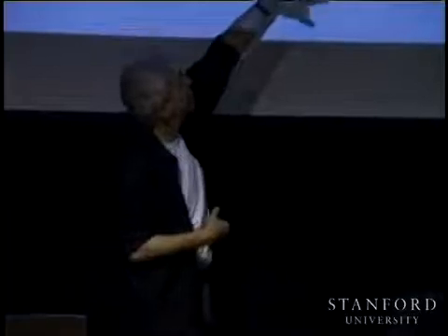You will have a sort of constant torque offset that will be divided by your Kp prime times m. That's not going to affect the stability. You will just reach the final goal position with a little error.